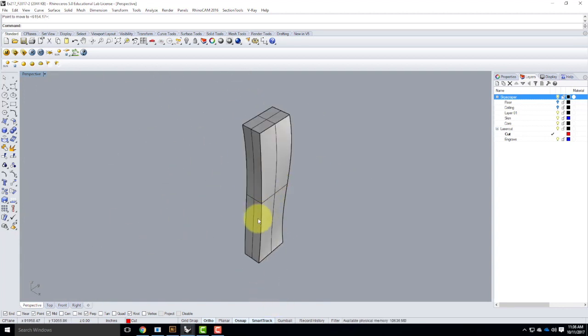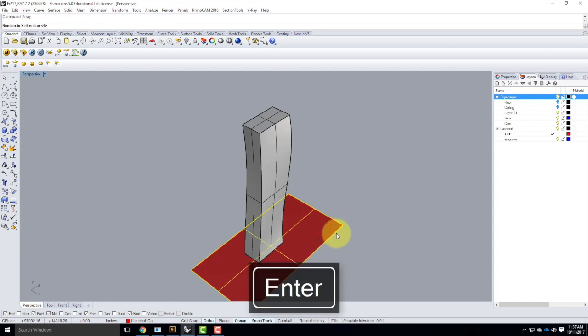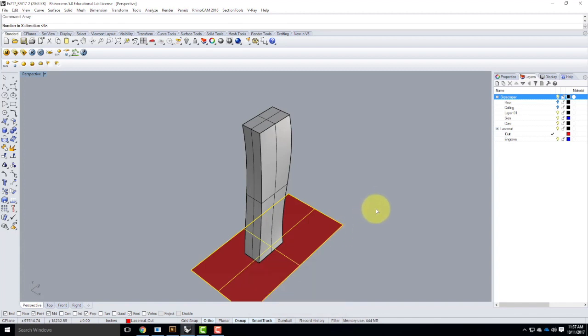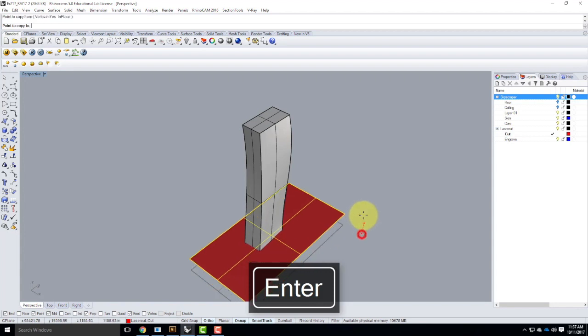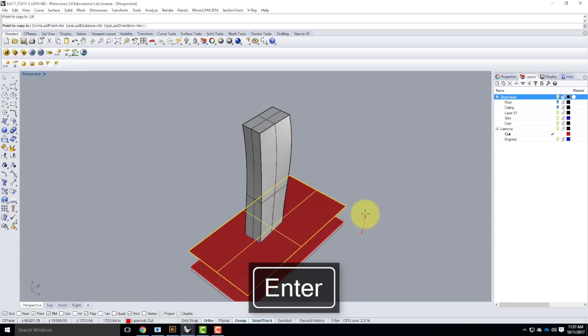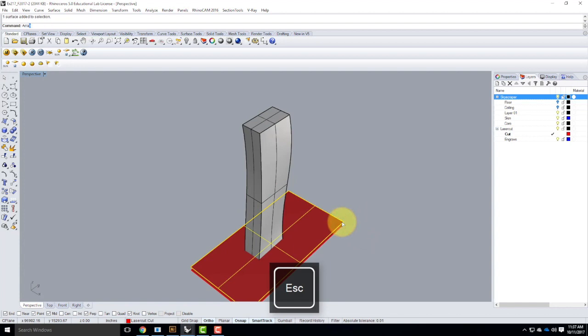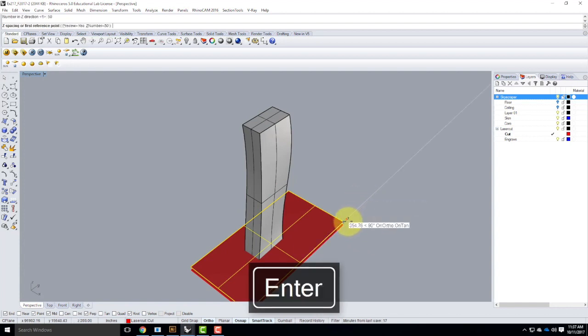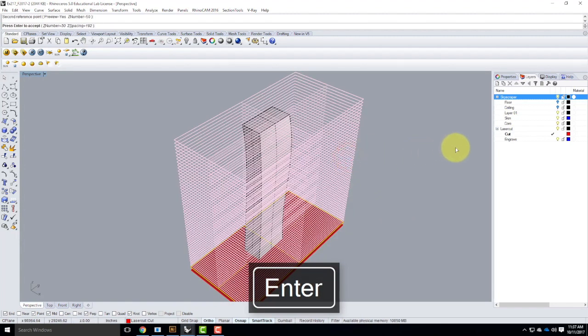And in this example, I'm going to put the floors back in. And I'm using the simple one here, so bear with me while I create the floors really fast. Let's array. And for clarity purposes, I'm just going to do one set of things here. So let me copy this vertical first. And then I'll array 1, 1, and 50. And it's going to be at 16 feet. That direction, perfect. Commit to it.